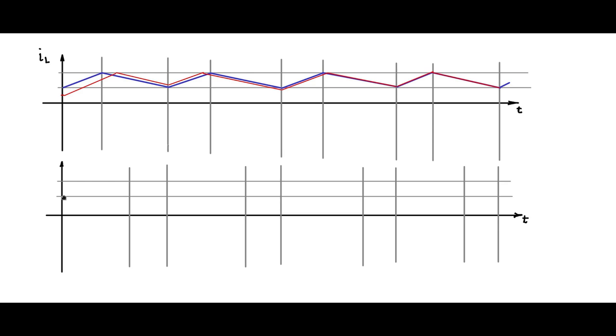And what is the steady state normal expected value of the inductor current? Let me first draw that. So this will be Vin minus VB by L. This will be minus VB by L, negative slope, positive slope, negative slope, positive slope, negative slope, and so on. So this is the normal expected steady state value of the inductor current under duty cycle greater than 0.5 also. Now here also, like here, we will introduce a disturbance. A disturbance has occurred due to whatever the reason.